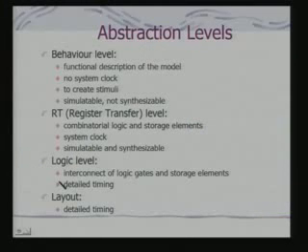Gates will have different timing depending on the technology that is being used for implementation of the gates. So, when we come to the logic level, we provide the specification in terms of actual logic gates and the corresponding storage elements. So, the detailed timing can only come at a logic level, okay, and the layout level tells you physically how these transistors are put onto silicon, what is their interconnect pattern, and that will provide you the absolute detailed timing.